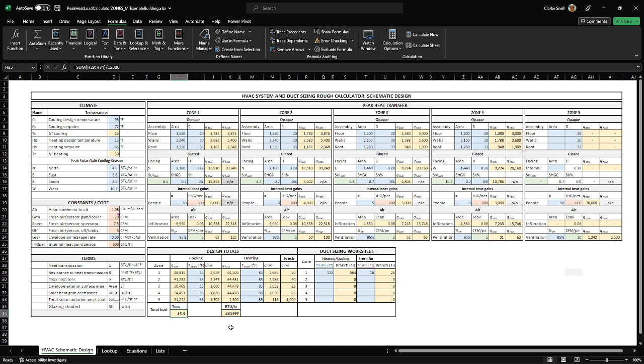I would suggest trying to look up equipment, and we have separate CFM requirements for each zone that we can then use to determine our trunk and branch sizes. If we're using ducting. If you're not using ducting, you don't have to do that. That's another thing we can talk about. I can't imagine not using ducting in the gym project. So if you come up with a way, great, but I'm not sure what it would be right now.